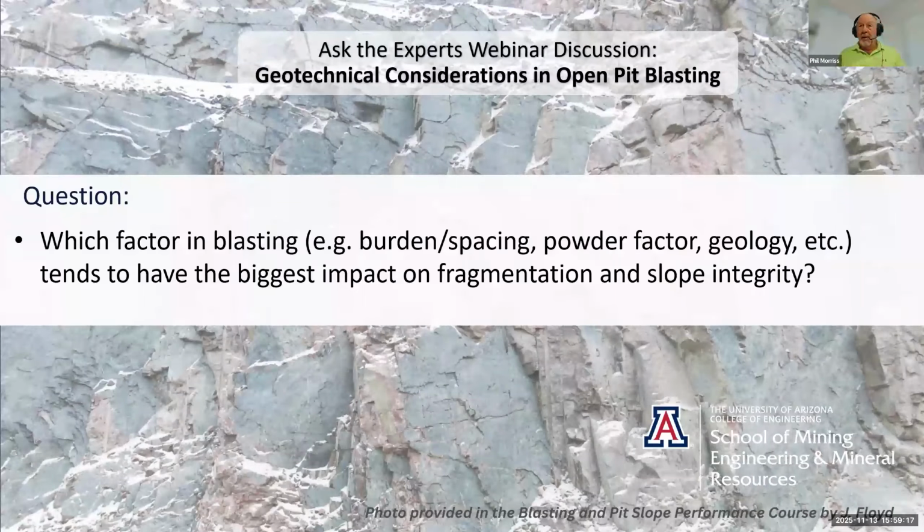If I could just add a quick one too, none of you have mentioned blast hole diameter. I see a lot of places where you do a lot of hard work with decking and messing around, if you like, but you're still working with relatively large hole diameters. Often the most successful way of controlling or improving slope integrity is to work with smaller holes and get better control of the distribution of energy in the blast. I'm sure we'll talk more about that anyway, and John can come in there somewhere too.